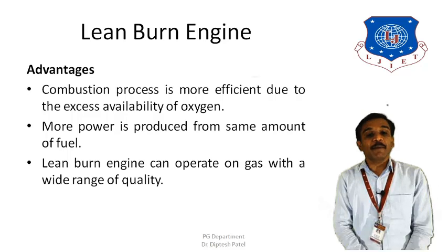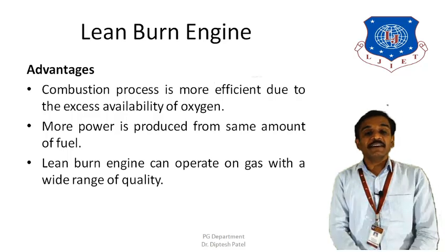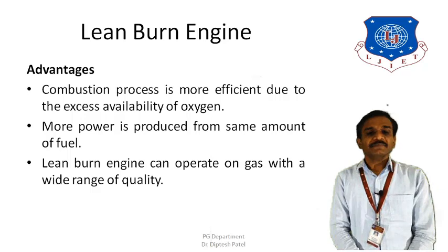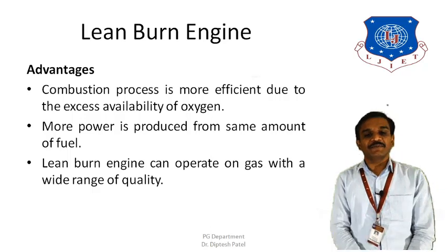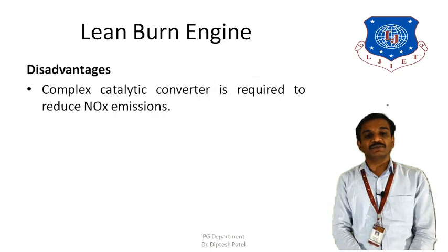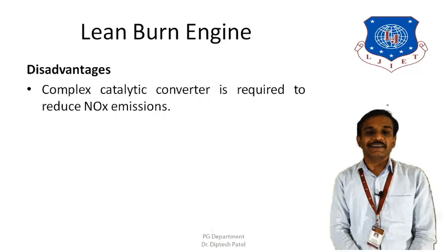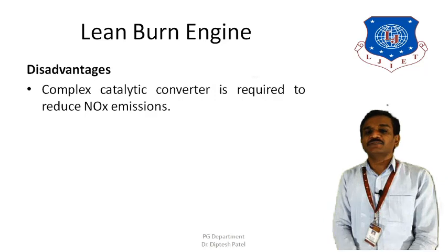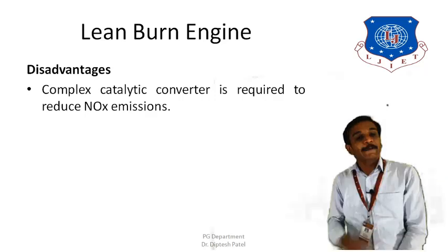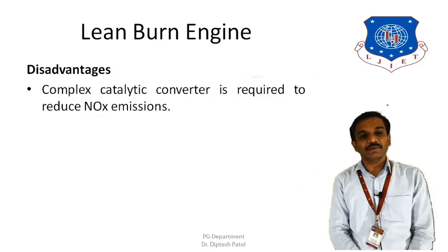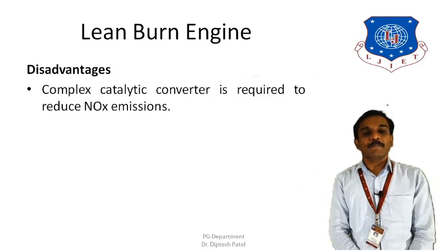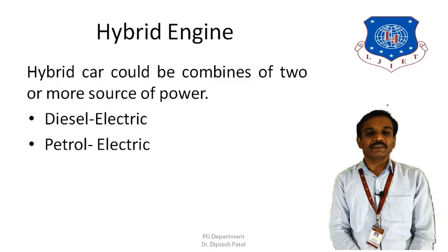And a lean burn engine can operate on a wide range of fuels. So this is also an advantage of the lean burn engine. Now let's go through the disadvantages. As I said earlier, the NOx emission is very high in a lean burn engine, and therefore it requires a complex catalytic converter to control the NOx emission. So yeah, this is all about the lean burn engine.